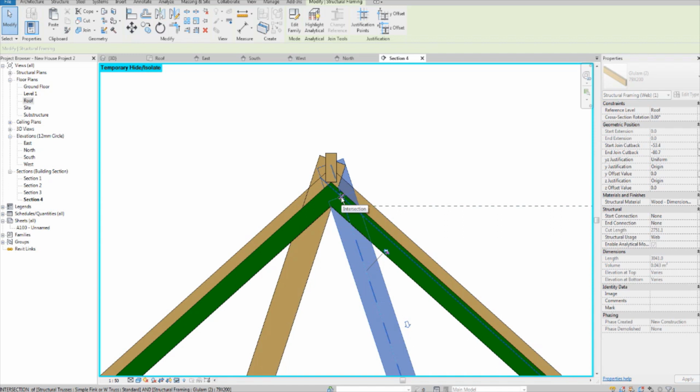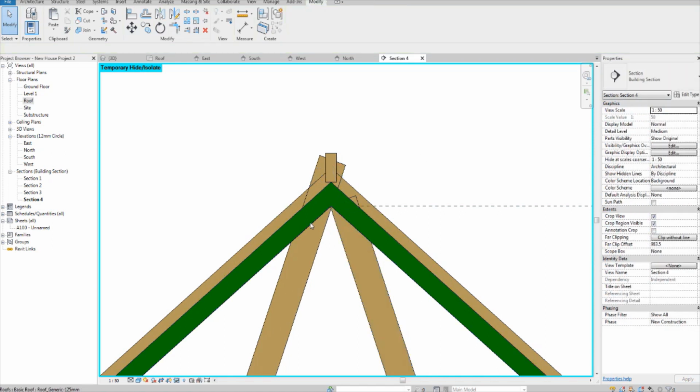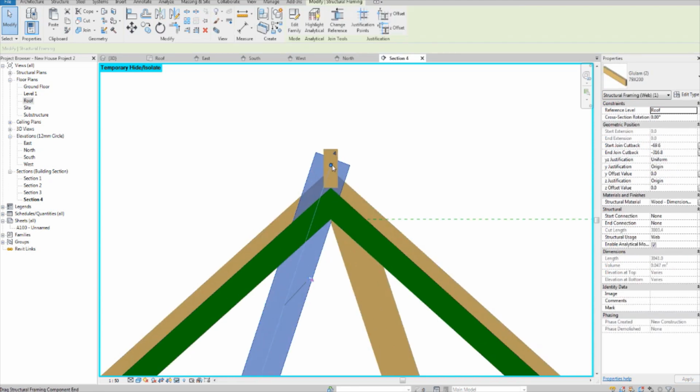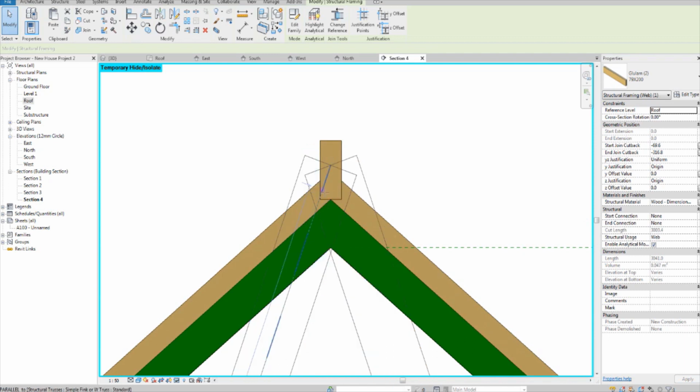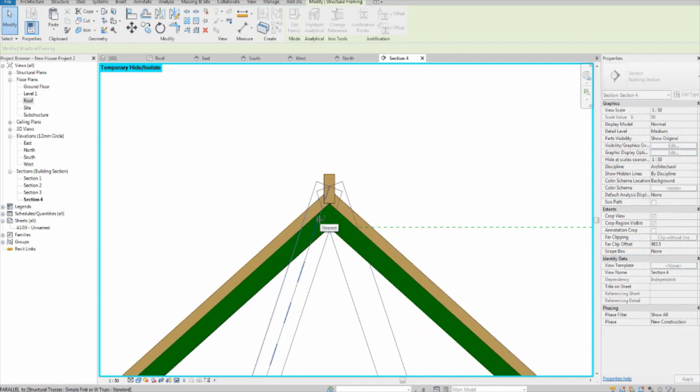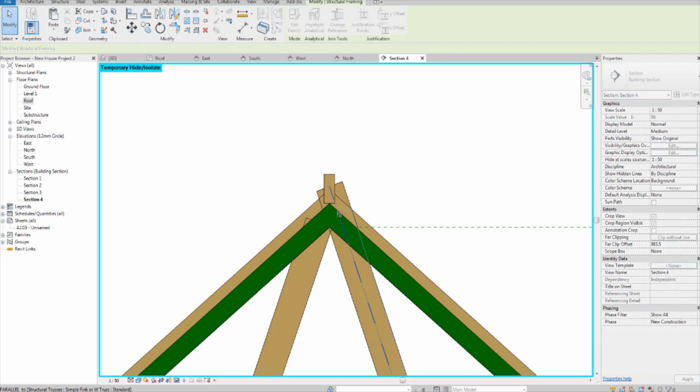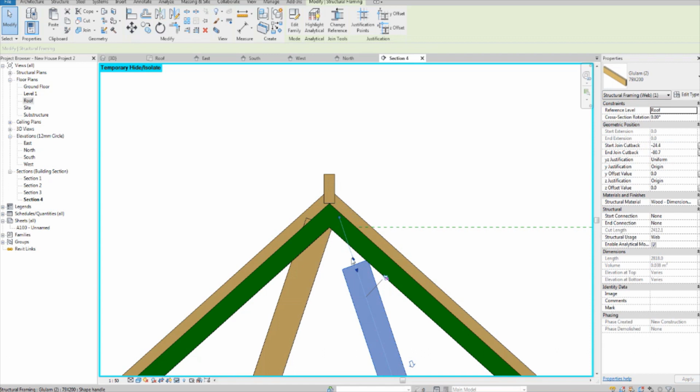When you're dragging stuff like this, hit SO on your keyboard to turn snaps off. Because when it snaps to anything, then it tends to change and go into the 5th dimension or something. You'll know what I'm talking about if you try it out yourself. SO. Let's drag it. Whoa, that's a bit far.